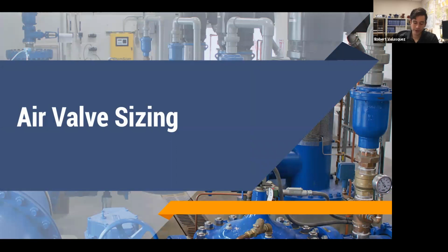All right, so we talked about a few different types of air valves. Something to note, today we're talking about AWWA air valves, so we don't have any plastic air valves. Those are becoming more popular in the market because they're really light and they're generally less expensive. AWWA doesn't approve them. They recommend ductile iron body air valves. So that's why we've been talking about these today.